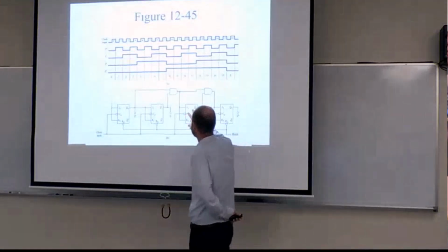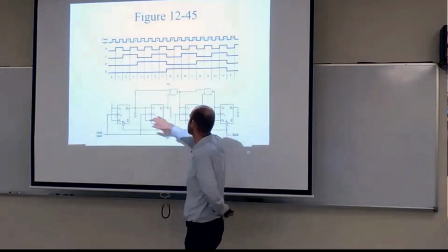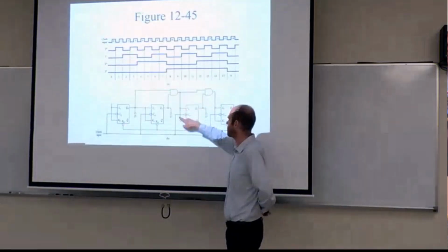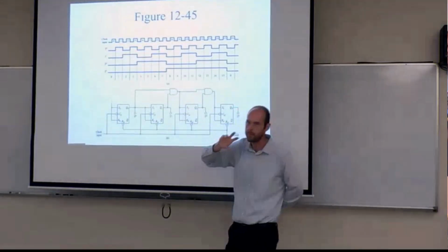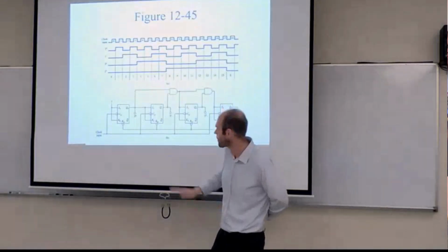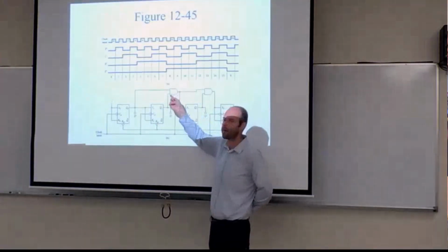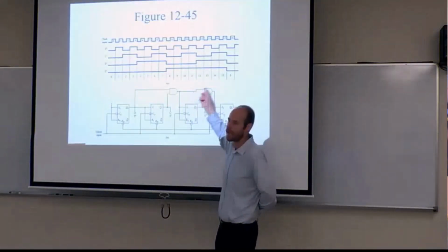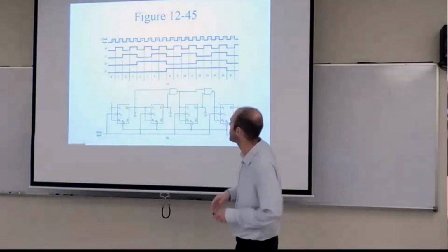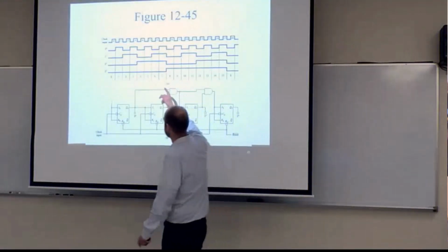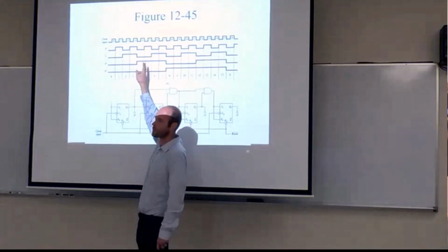And the third bit now has this AND of the first two. So we're going to need to count up to 1, 1 before this bit will get its toggle operation to happen on a clock. So while we don't ripple through every single circuit, there is still potential propagation delay from singular gates, for example. But basically all this is doing is setting up the timing diagram so that this third bit will only flip when those first two are high.